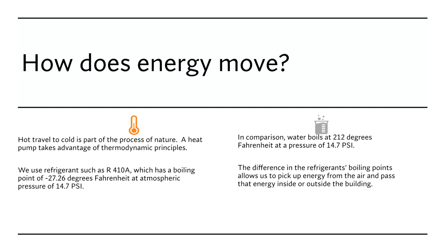Okay, so that being said, R410A has a boiling point of minus 27 degrees Fahrenheit when we're at one standard atmosphere, which is 14.7 psi at sea level. We'll play with it at sea level, even though most of northern New York is about 400, depends if you're up in the Adirondacks, you could be as high as 1,800 feet. So depending where you are, but we're going to play with sea level for the time being.